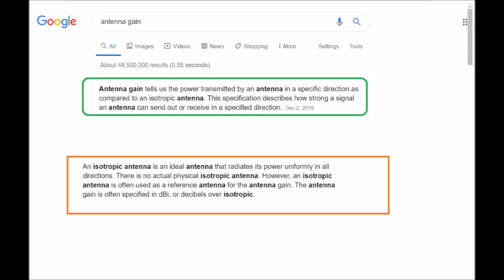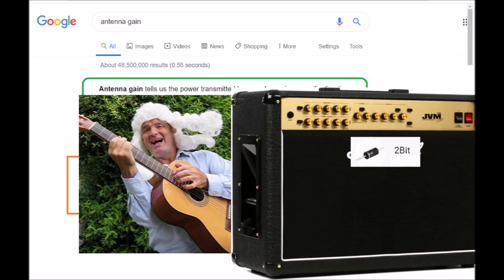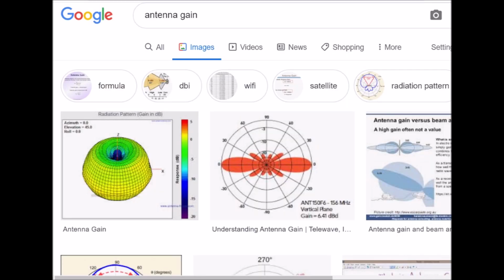Antenna gain describes the concentration of radiated power into a particular solid angle of space. Gain is perhaps an unfortunately chosen term, by comparison with amplifier gain, which implies a net increase in power. In contrast, for antenna gain, the power increased in the desired direction is at the expense of power reduced in undesired directions.